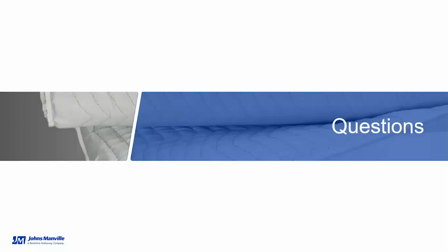Great, thank you. The next one is for you, Mary Beth: how does the water leave the system with weep holes if the InsulThin is hydrophobic and would trap the water inside the covered wet insulation? That really comes down to how the InsulThin is installed. In order for the water to leave the system, you have to make sure that the seam is facing downwards where the weep holes will be, so that the water can drain out of the system through the InsulThin, even though the material is hydrophobic. Great, thank you, Mary Beth.